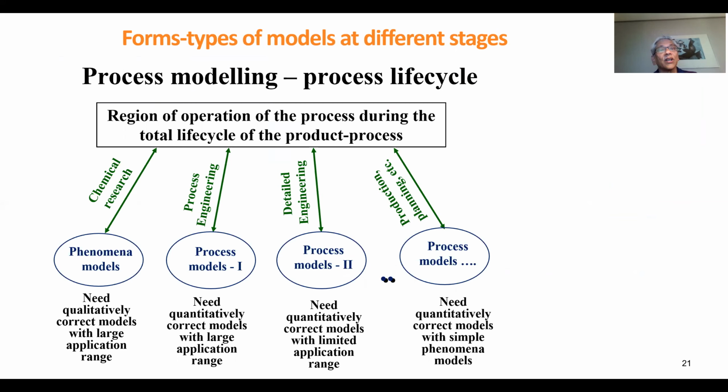And that's the reason why we have to think of the importance of thermodynamics and the phenomena that is occurring in the processes that we are studying, because while the process model at different stages in the life cycle will change, the phenomena model will not. If the same chemicals are being used at the same conditions, then those properties are fixed, and the model that gives those properties is fixed.